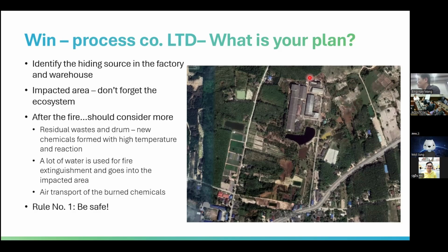And then you can use at least maybe 10 or 20 sampling points. You can get very preliminary information on the distribution. And based on the information from the groundwater department, which has already told you, there is about an 8 to 10 meter sandy layer, right? And you know the bottom of this sandy layer.